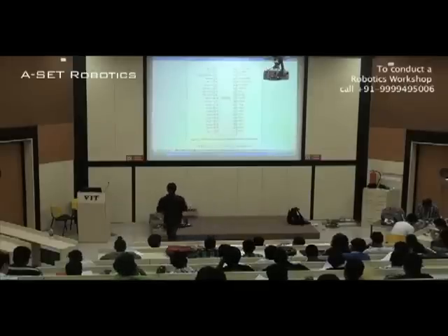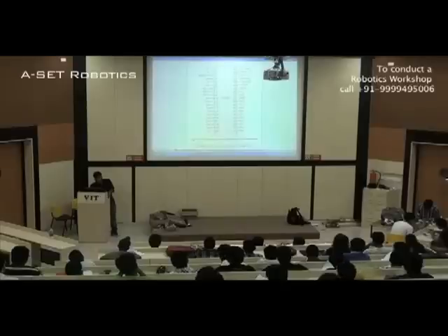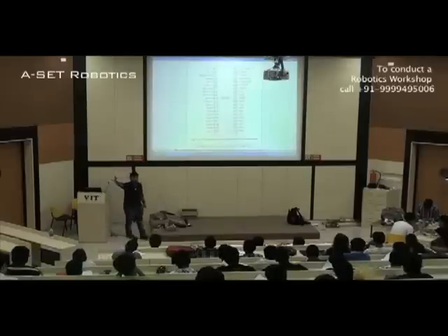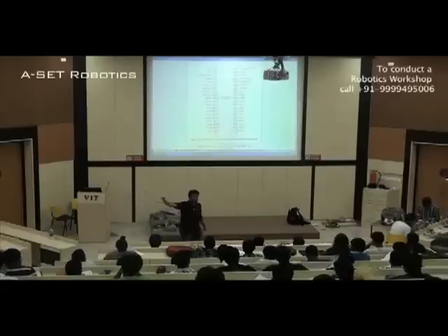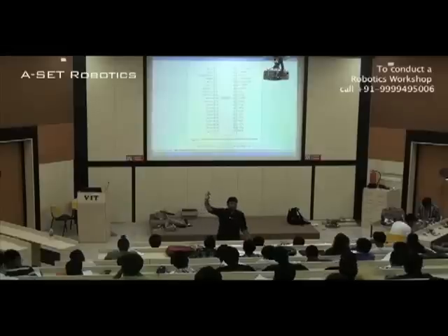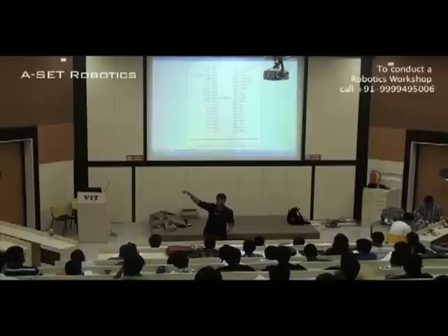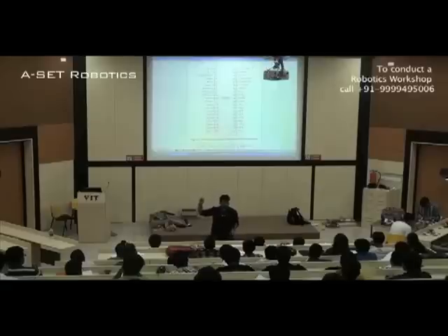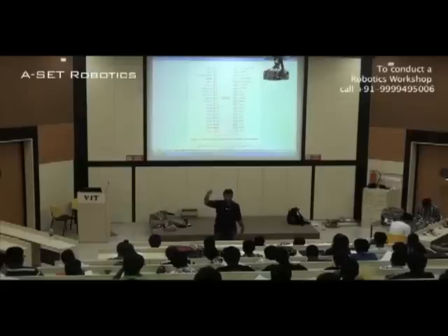For the DMA to work, it gives a signal to the microprocessor: hey microprocessor, hold right there. What signal does it give? HOLD. Whenever the microprocessor says, okay, I'm waiting right now, it gives a signal, HLDA, hold acknowledge, back to the DMA. And the DMA gets to know that, okay, now my microprocessor is not doing anything.